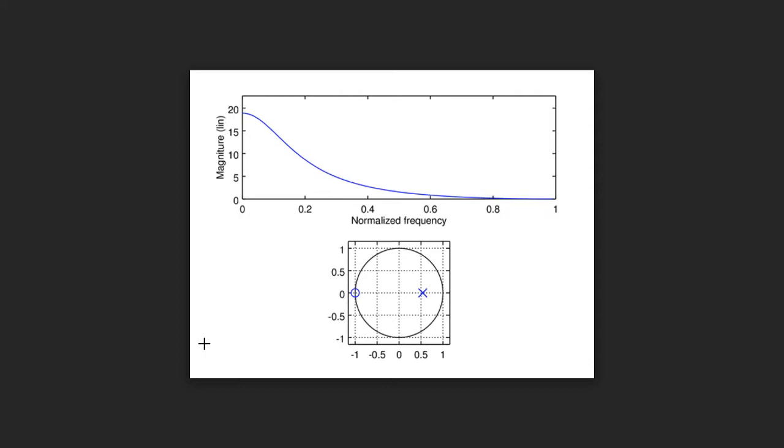Great. I'm now moving the pole away from the zero. As you can see, the Q factor actually goes higher. It's the same thing as in analog systems. When you get your pole close to the imaginary axis, you actually have a high Q factor filter. And the same thing over here, going higher, higher, higher. So we also have a narrower filter here.